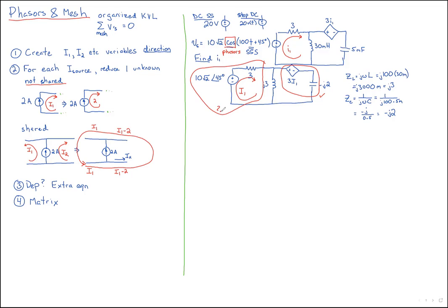You can't, because that would destroy I1, wouldn't it? So that's an interesting thing. Watch this. If we were to source transform to the left of this, it might seem like it would destroy your I1, but look at this. Your I1 actually exists outside that. Agreed? Yeah, but doesn't it also exist within that? It does. And the I1 that exists inside it would be totally destroyed. But the I1 that's outside it does not get destroyed.